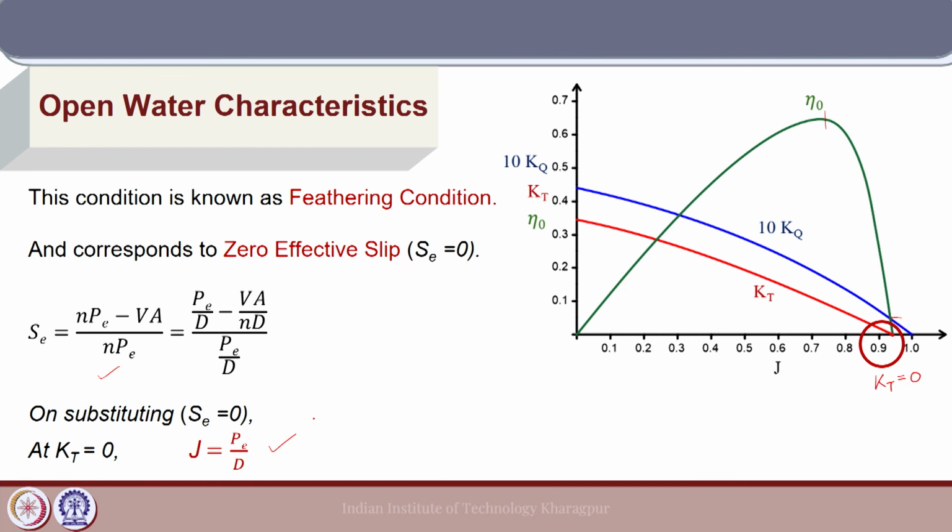Okay. So, propeller open water characteristics is very important in the context of marine propulsion, because when we try to understand the characteristics of a propeller as a separate entity, open water diagram is the basic estimate of the propeller thrust and torque with the change in the propeller loading condition, which is J. So, different propellers will have different thrust and torque characteristics, which will be given with the help of open water diagram. So, this is the most standard way of expressing propeller characteristics.